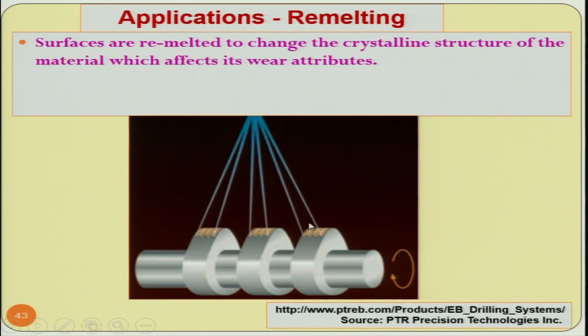See, this is one particular part, and this is the area which will have maximum wear compared to the rest of the area, because this is a discontinuity, it is coming in contact at high pressure with other material. So this wears out. So you want the material here to be deposited which has very high wear resistance. So the question is how to deposit it or how to melt it and deposit it.